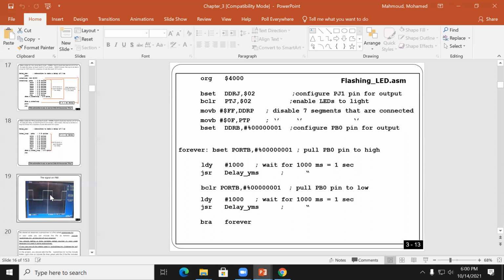Look here, guys. In your program, you should have org, as I explained before, org 1000, and all your data definition should be here. And then you should have org 4000, and this is your program here. What we did so far was the main program. We didn't have subroutines. So all the labs we had before, we didn't have subroutines, just the main program. So the subroutines should come here, after the main program.